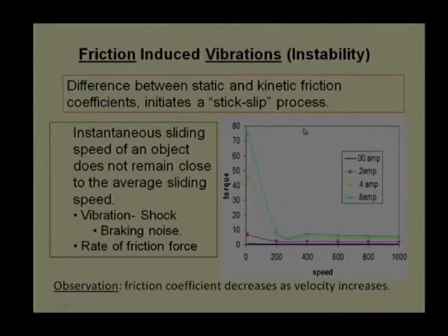It is reaching one steady state condition. And if I remember kinetic coefficient of friction and static coefficient of friction, we say that the static coefficient of friction we can calculate at the first point, just at the start, and the kinetic coefficient of friction when it reaches the steady state condition. But the difference in that coefficient of friction is almost 6 to 8 times.